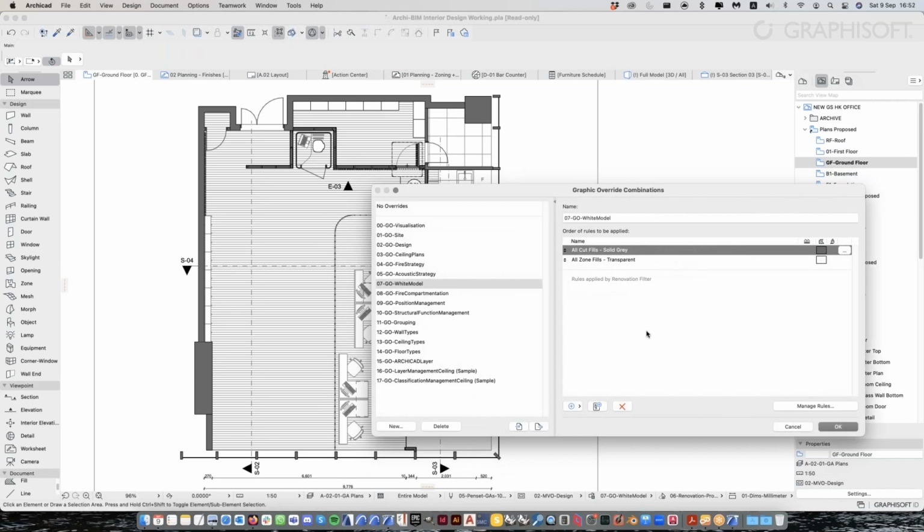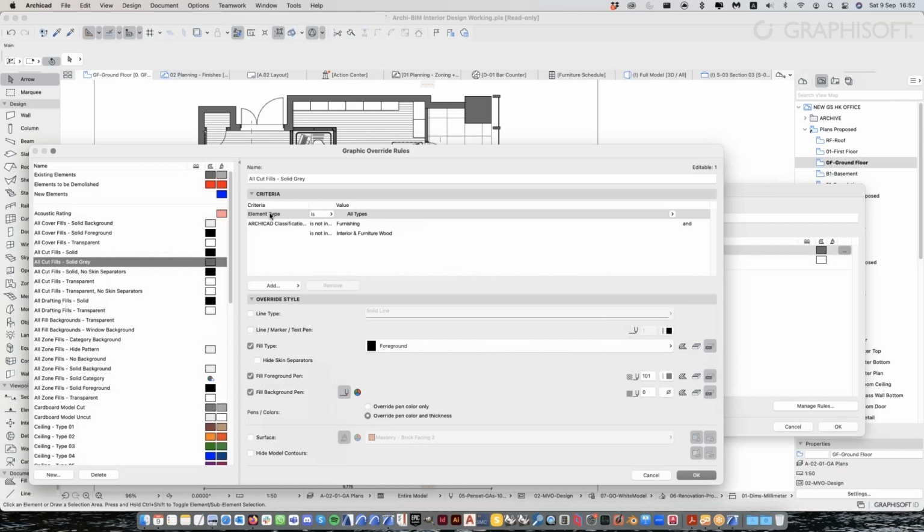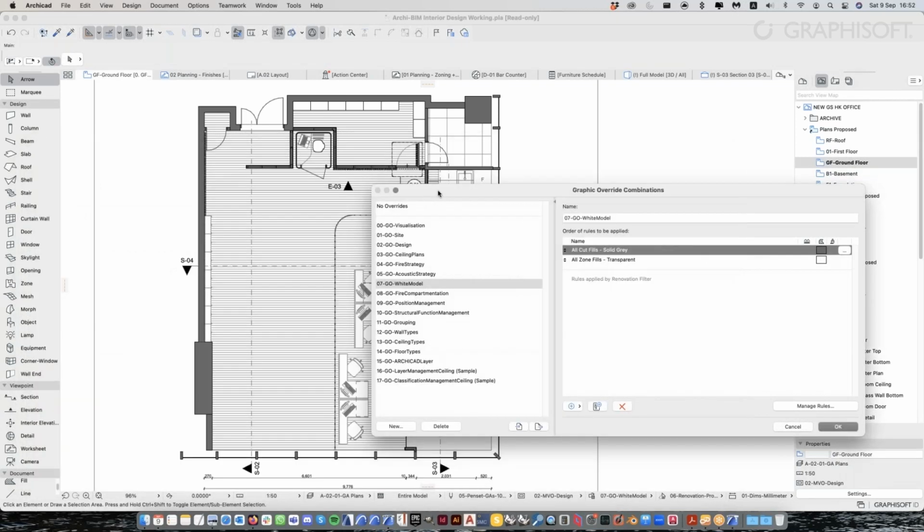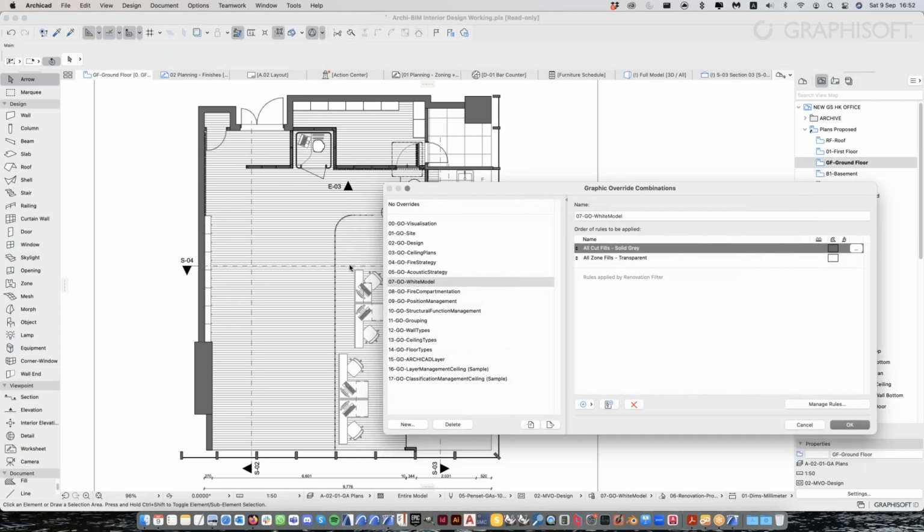For example, if I want to highlight furniture that is of this size to all be red, then I can create a rule saying, element type is furniture, and maybe width is 200 by 200, height by 300, etc. And to highlight them all in red, then once this is applied, whatever elements are fitting that criteria will be highlighted. So this is how the graphic override will work.